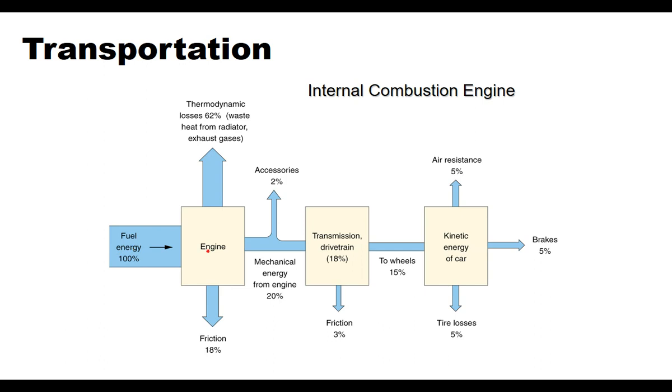You're burning your fuel, your gasoline coming in or your diesel. The engine is going to send about 62% of its energy out as heat. So that'd be heat coming off of your engine. Another 20% or so is the friction of turning the motor. Motors do not turn very easily, even though there's lots of lubrication and stuff in there. So you get your mechanical energy that's now leaving.